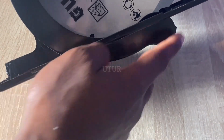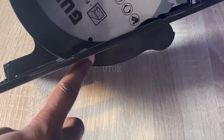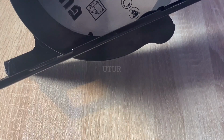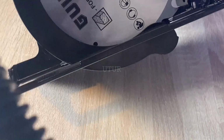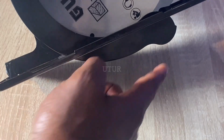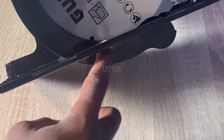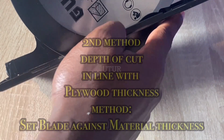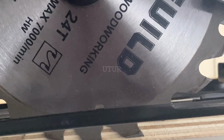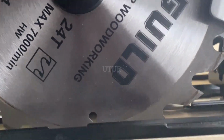And so basically we have set the depth of cut in line with the thickness of the hardwood plywood that we want to cut. If you don't know the thickness of the material that you want to cut, just set the blade beside the thickness of the material directly, just underneath the base plate, and then subsequently adjust the depth of cut scale accordingly.